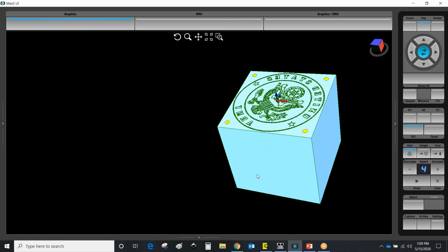Well, I can take that 3-axis G code, put it inside a conversational transform plane to put it on the front. And if you're not sure how conversational transform planes work, that was one of the recorded webinars we've done in the past, so you could go back and take a look at that. On the Hurco website, if you go to the support tab, there's a link to all the recorded webinars, and this will become one of them after today.